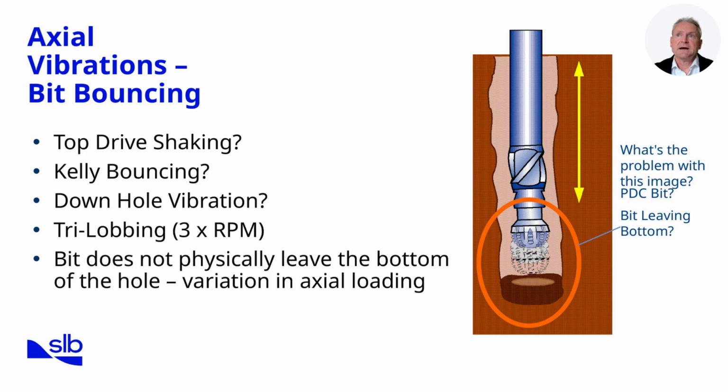On the right-hand side, the image challenges us with a question: is the PDC bit leaving the bottom? The point here is to recognize that bounce is not the same as bit liftoff. Instead, it's about stress cycles that fatigue components and reduce efficiency. Understanding axial vibrations is critical because they reduce rate of penetration, damage cutters, and shorten tool life. With this foundation established, let's move next to how we mitigate axial vibrations using shock subs.